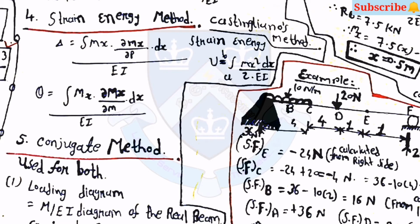Then the fourth one is the strain energy method. For this method, the equation of delta is equal to integration of M into x into del Mx upon del P into dx divided by EI. Then theta is equal to integration of Mx into del Mx by del M into dx divided by EI. And here the equation of U will be integration from A to B of Mx square dx upon 2 into EI, which is the equation of strain energy. This method is also known as Castigliano's method.